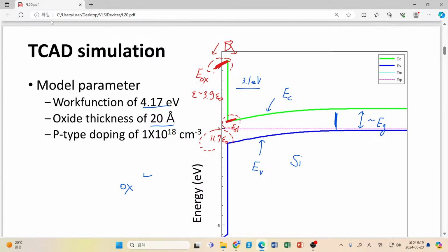So today we will talk about our band structure, and please try to find our mid-gap energy or intrinsic level. So maybe you can find somewhere here our intrinsic level, and also you can identify the difference between this level and here we have a Fermi level of our p-type substrate. So here we have a certain difference, and this energy difference is given as q times phi b.